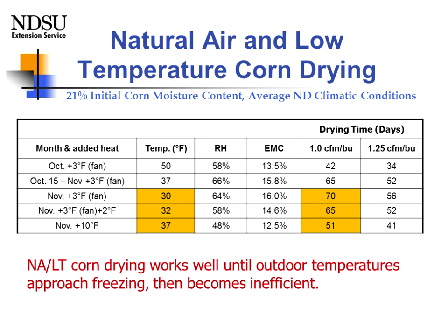Still, the moisture content isn't too bad, but we see the days required to get that drying done going up considerably. As we go to November, where our average temperatures are down near 30 degrees, we see that we're clear out to about 70 days of fan time to get that dry.